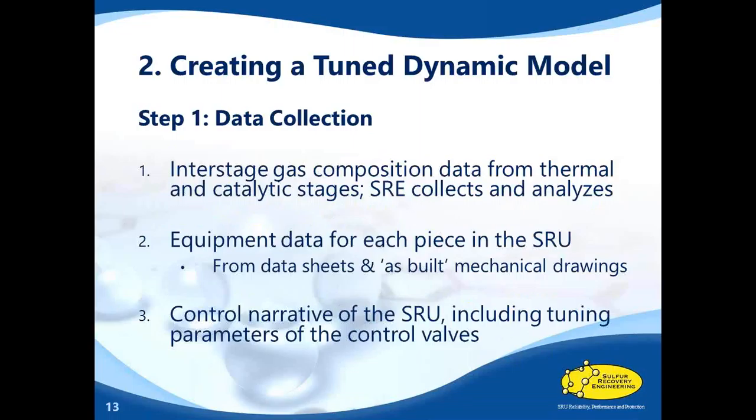So the first step in everything is data collection. You need to collect information with regards to how the unit's performing in its current capacity. So what we had to do is collect interstage gas compositional data from the thermal and catalytic stages.